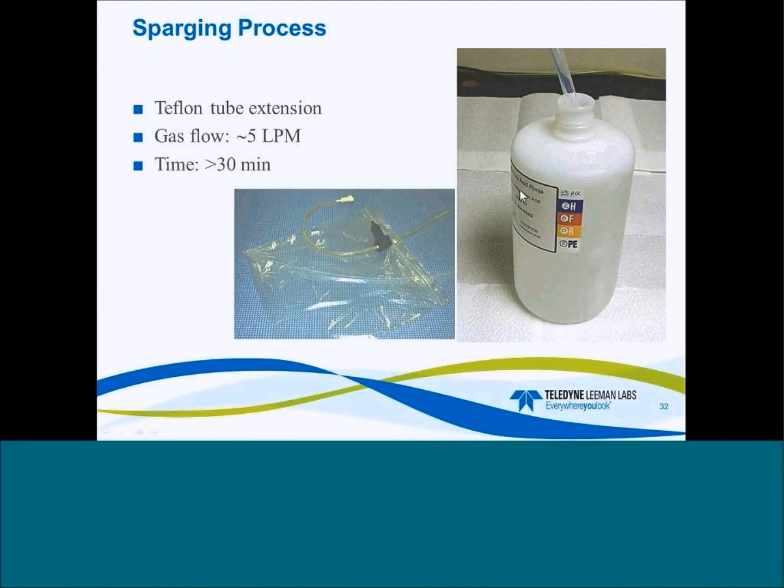If you're going to use a rinse station on your sampler, then one of the suggestions is to add 1 ml per liter of stannous chloride reductant to that rinse solution and bubble it. This is called sparging, and that process will, just as it would release mercury in the normal analysis cycle, release mercury from your reagents.